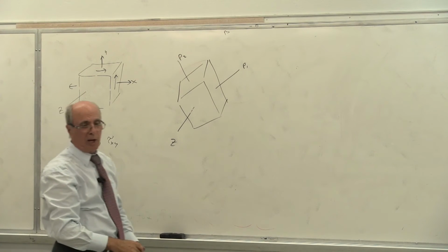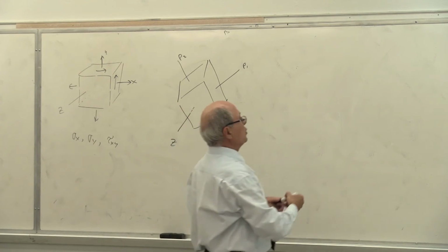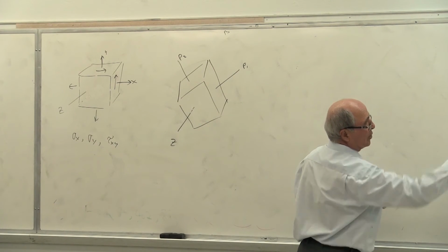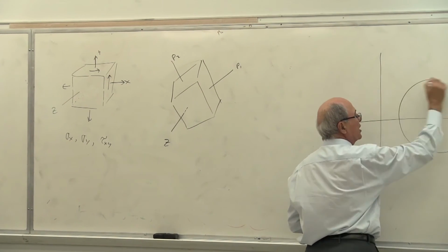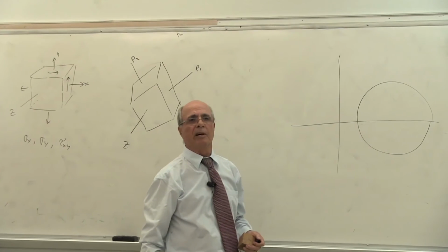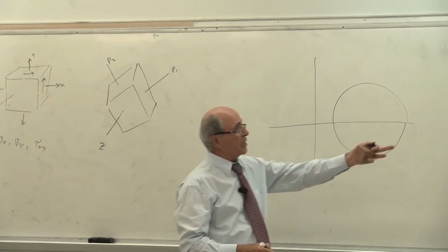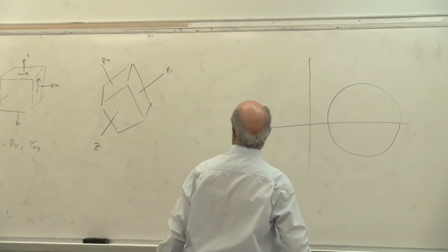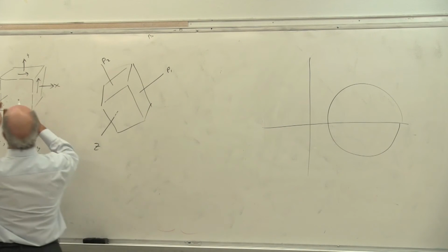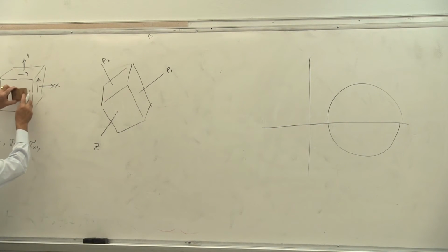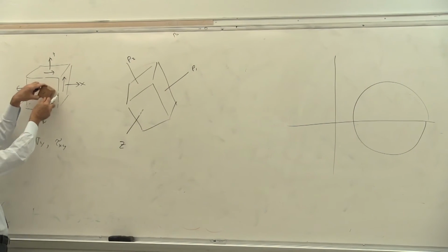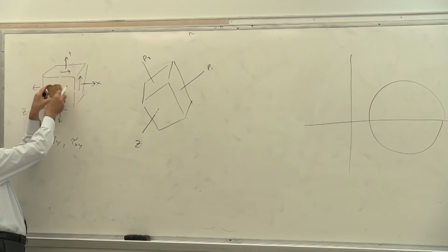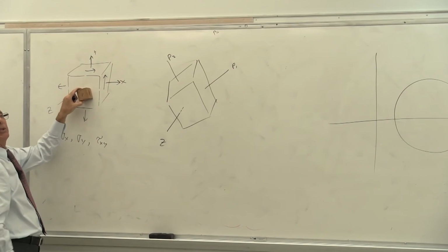Very good. So what I want you to write is this. You draw. Forget about that. That's for reference. So you draw this. Okay, you come up with a circle, any circle. Is that correct or not? When you end up with that circle, similar to that or similar to that, you do this rotation one more time. When you want to get rid of that shear, you go clockwise or counterclockwise to get rid of the shear to come to the principal stresses.